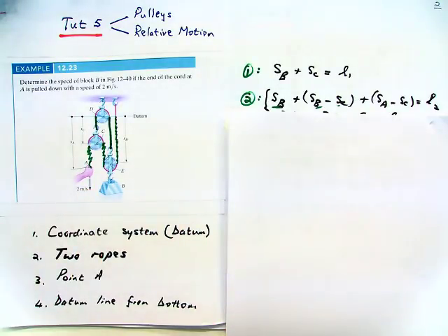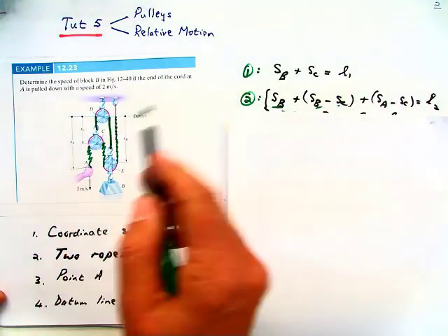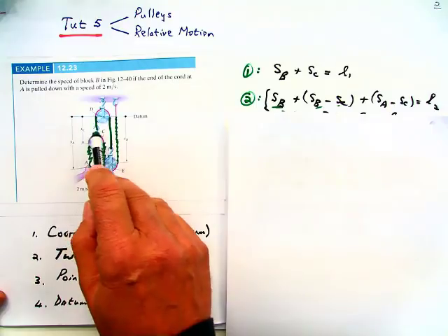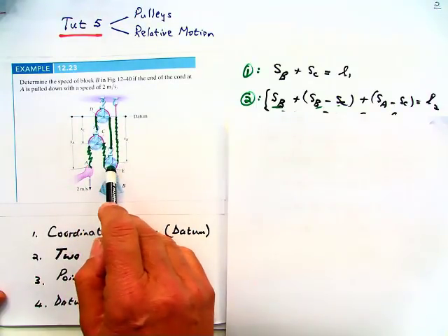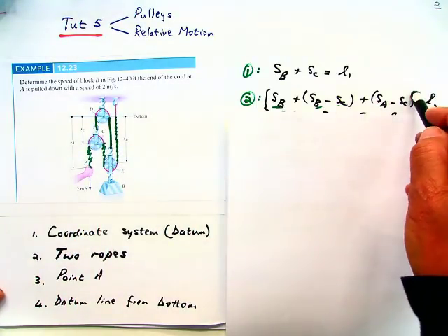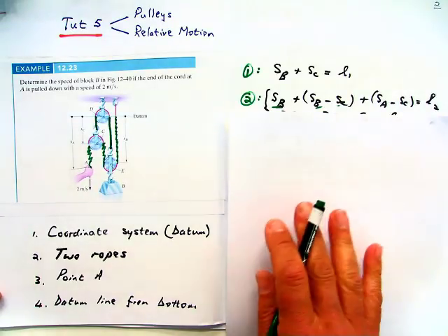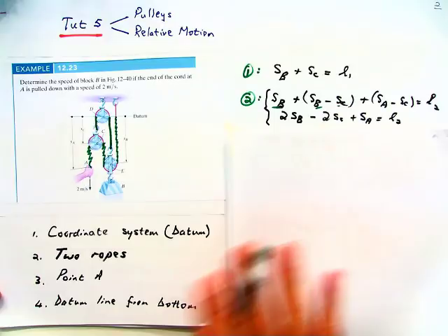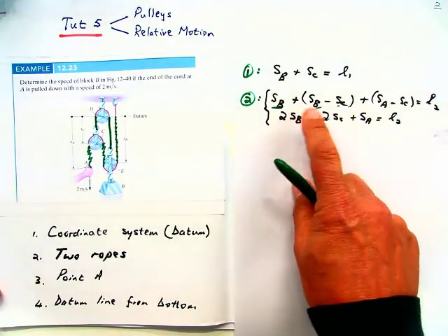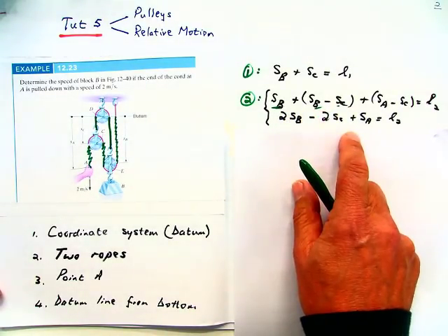Because your rope is a non-elastic rope, the length of the rope stays the same. It's not going to change. The relative distances are going to change, but the total length of the rope is not going to change. And as I say, you can add this constant distance here and this one over here, but it's just a constant on the left-hand side. You take it over to the right-hand side, it's still a constant. So that one, if you simplify it, you get this equation.